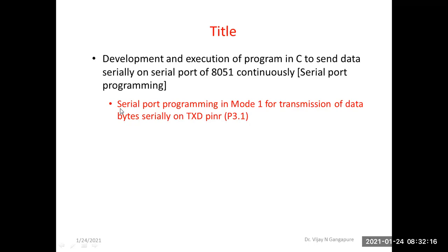In particular, we are going to study serial port programming in mode 1, that means 8-bit UART mode, that is the number of data bits sent asynchronously is 8 bits, for transmission of data byte serially on the TXD pin, that is pin number 1 of port 3. So we are going to study serial transmission in this practical.